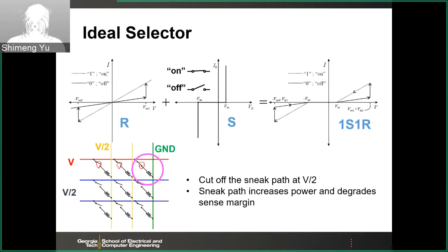So here, for example, this is an ideal resistor. You have 2 values, the low resistance state and high resistance state. In the I-V, you have 2 slopes, you have 2 resistances. These are 2 states of this memory cell. And what you want is to have an ideal switch like this. There's some threshold voltage. And above the threshold voltage, the current will be very large. And below the threshold voltage, the current is almost 0. So it's like an ideal switch with this threshold voltage.